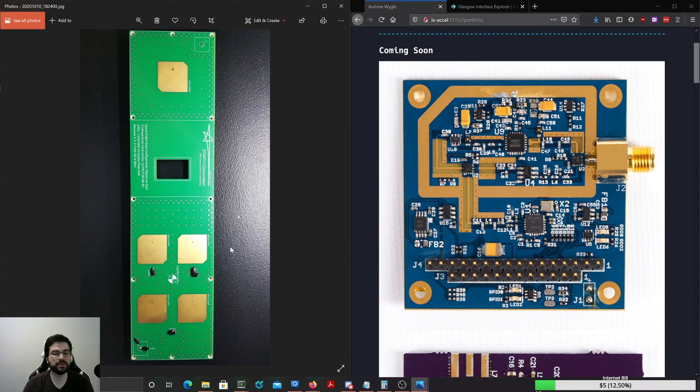Its design was basically to give us high gain for high data rates, and then also low gain for reliable communication. But you can't really do low gain at S-band with a patch antenna. It doesn't really work. So the best we were ever able to get out of this is like a half sphere coverage, which is not good enough when you're an uncontrolled tumbling CubeSat. This is another reason why that mission was pretty much doomed from the get-go.